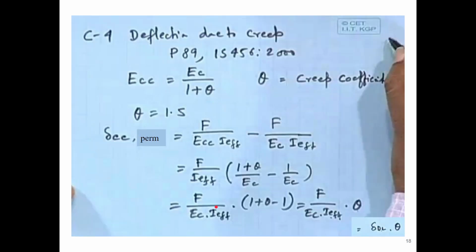So that is shrinkage, and one more deflection is there, that is the deflection due to creep. Shrinkage mainly occurs due to the evaporation of water inside the concrete pores. And creep is the long term deflection, after the instantaneous deflection occurs, and it reduces with time. So that is long term deflection basically.